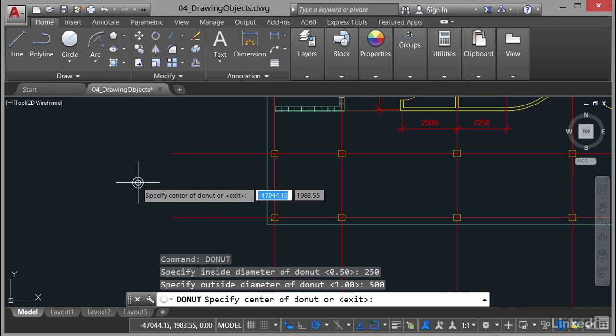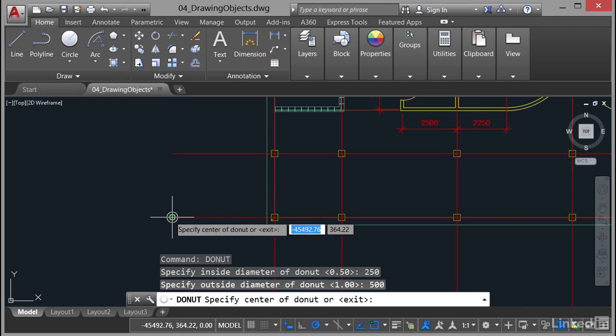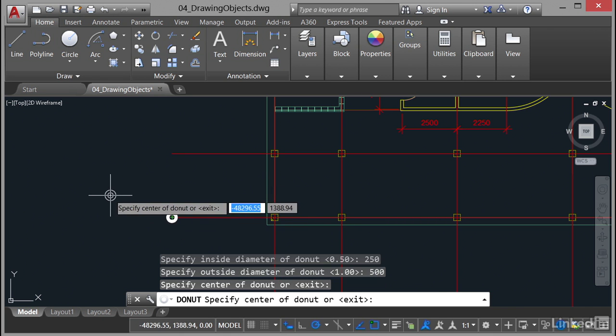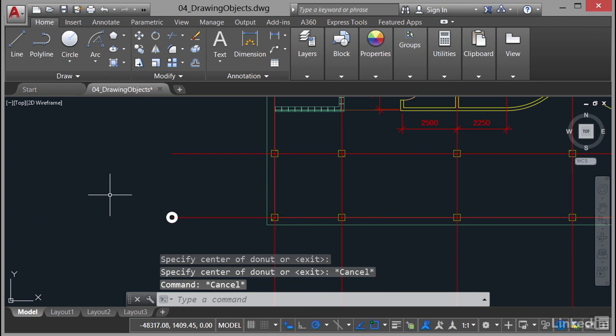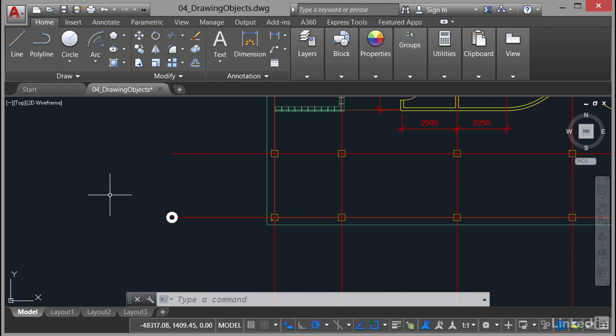There's my donut. You can see it now on the crosshair. I line that up with the endpoint snap and I click, hit escape to deselect or cancel the command. And there's my donut. Looks a little bit like a little white polo mint, if you remember polo mints. But I think they're a British thing. So you Americans might not get that, again, with the spelling of donut and so on. Kind of playing on words a little bit there.